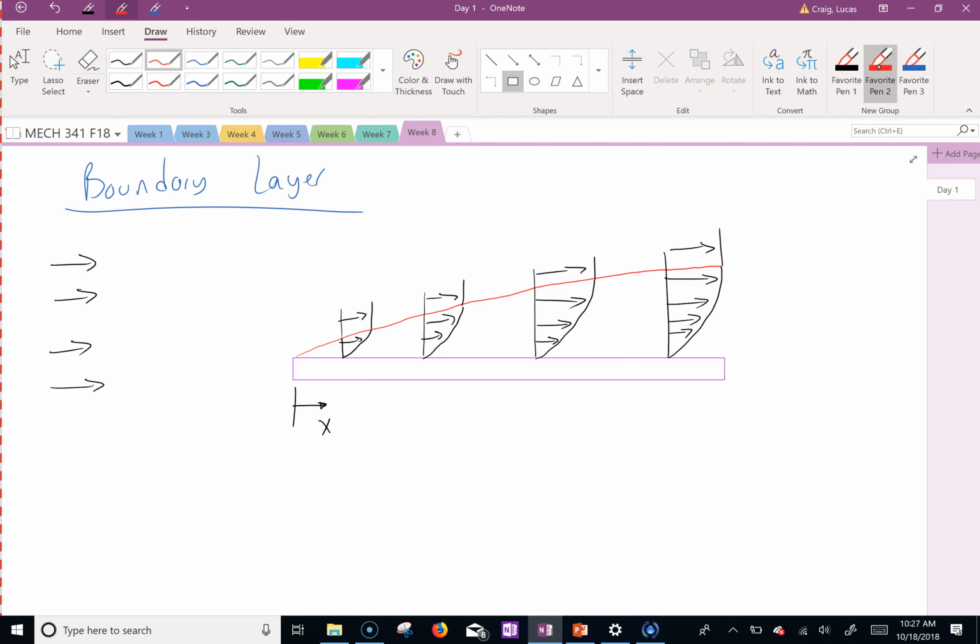And what happens is when it first touches the surface, the velocity at the surface is 0. It sticks. And then as it keeps moving down, all this velocity is 0, and it's grabbing more of the molecules above and slowing those down. That's why this grows to the right. Does that make sense? So any object, you're going to get this boundary layer. Now, it's not this dramatic. Sometimes it's really, really small.